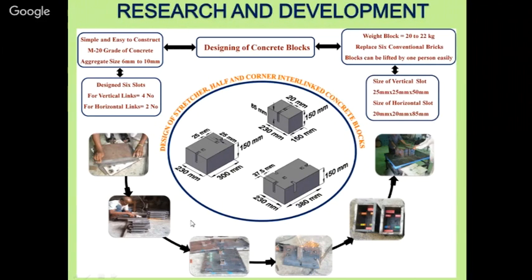Now we have developed these concrete blocks with M20 grade of concrete, with the mix 1:1.5:3. For developing these blocks, we have developed block molds having these grooves. And the beautiful part of this technology is that we have not used any cement mortar for joining these concrete blocks with one another.